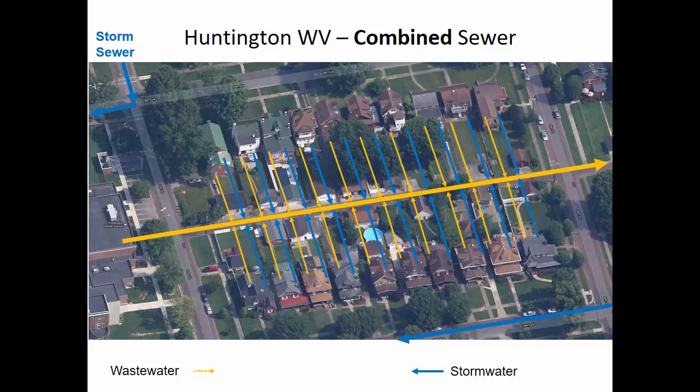And so there still are other problems, though. There's something called a combined sewer overflow. In the vicinity of Ritter Park, for instance, if you ever are over at Ritter Park the day after a storm, if you're walking along Four Pole Creek, you can kind of smell there's sewage in that creek. And so if the pipes don't have enough capacity to convey flow to the wastewater treatment plant, then they're designed specifically to discharge the water into the nearby creek.